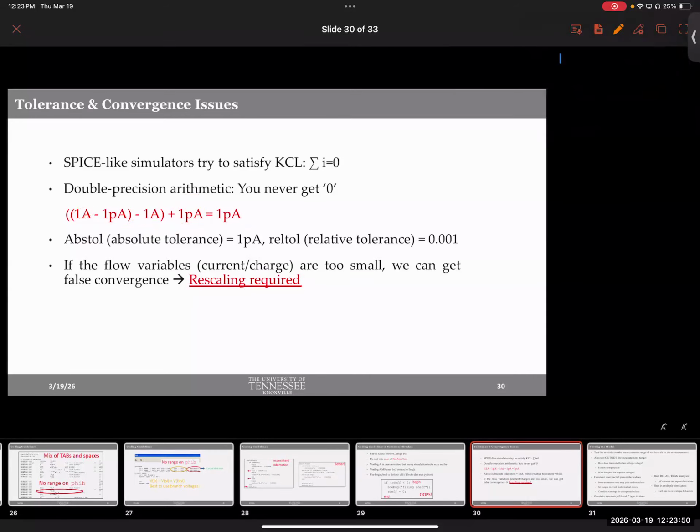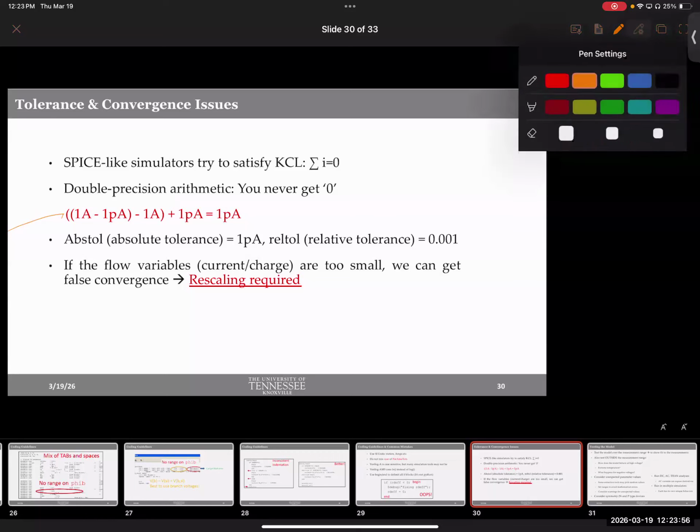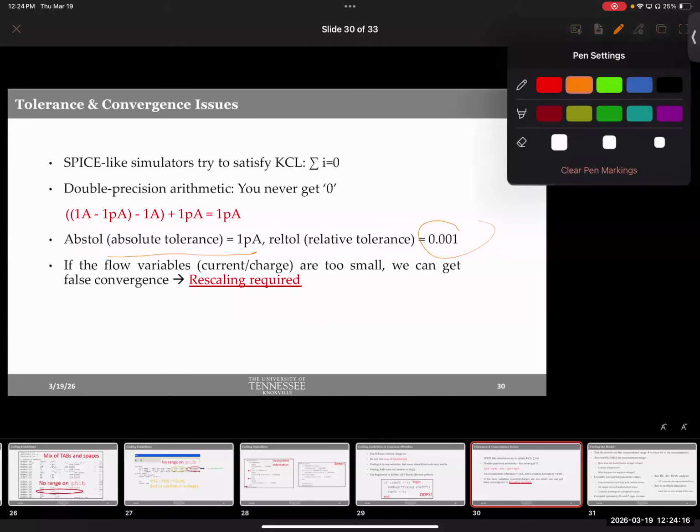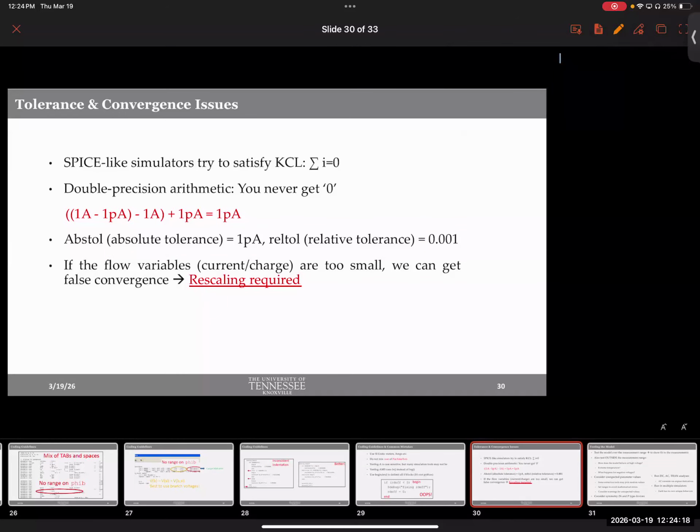I told you, I'm not trying to make you make the models because that can be very painful if you're doing it right and including all the possible considerations. But using is not that difficult. You can always use it and modify if you want. Okay, so there is something called absolute tolerance, meaning you're saying the tolerance is 1 picoampere. Or you can always mention it as a percentage, 1% tolerance of whatever the value is. Both are possible to set.